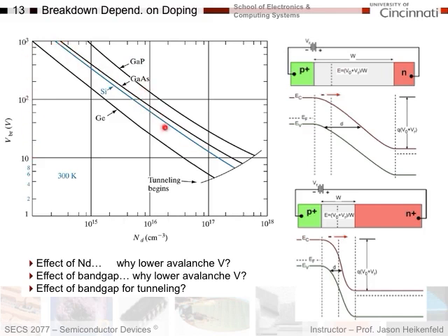So this is all avalanche breakdown, these curves here. I basically increase my doping level, that brings in my depletion region, I get a steeper slope, so my electron doesn't have to go as far to have enough energy to relax and basically create a second electron-hole pair, and so on and so on.